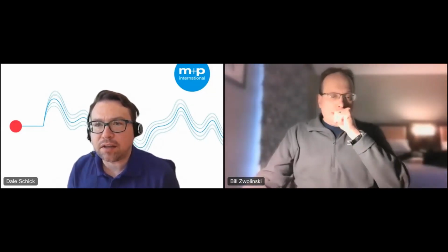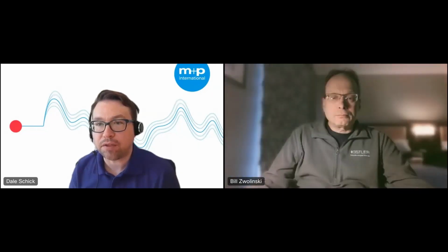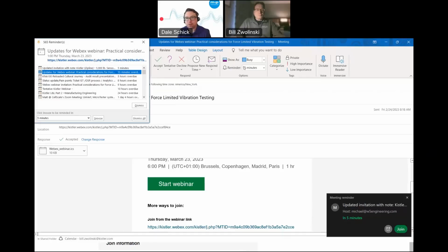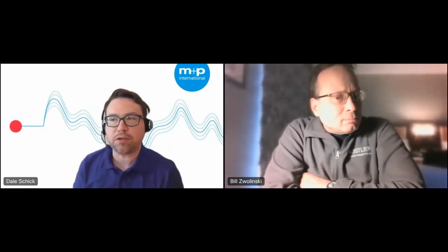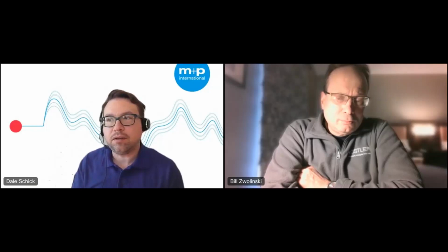We have another test that says they have CG acceleration limits with component responses, and their low frequency breakout models that include an FEM of the surrounding vehicle structure. What do you gain from force limiting testing versus an acceleration limited test? This is from Tyler. I think acceleration limits are easier to implement, but the thing to consider here is what Bill mentioned earlier, in that the impedance of the shaker table is almost infinite.